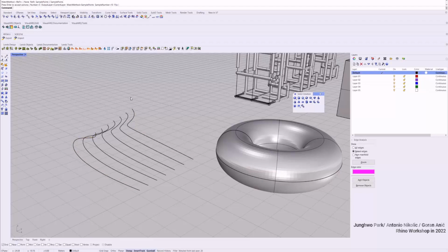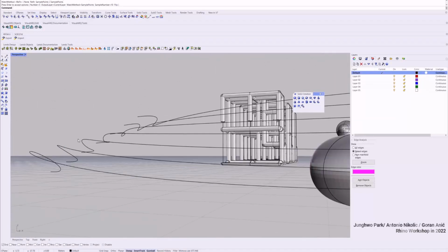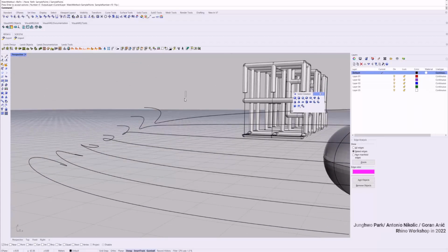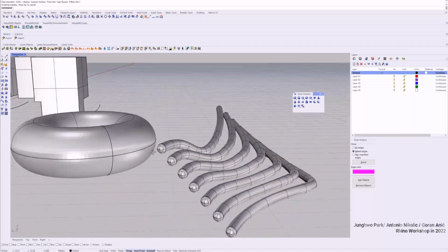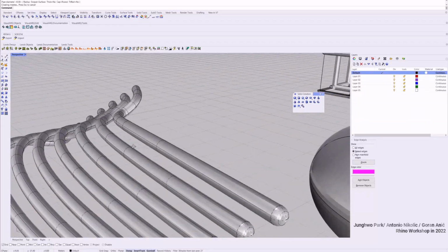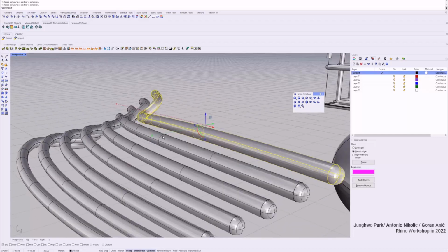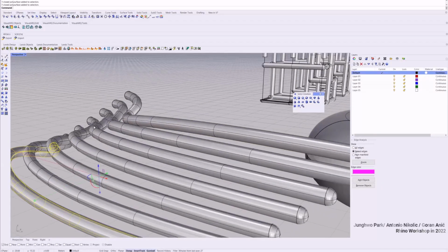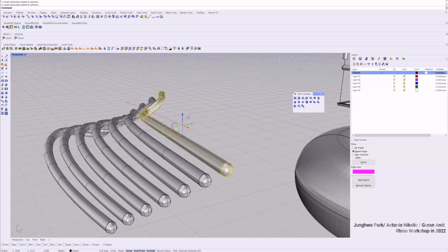In this, it's not exactly the same curves, but you need to convert it as conduit. Then you can model it in Rhino, and this one you can send as a Revit family, and add parameters and everything. With the Rhino Inside command part you can set a shared parameter for this, but the geometry is not parametric geometry.